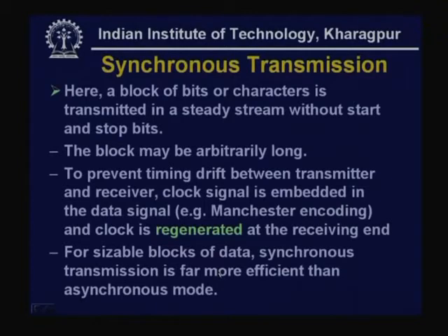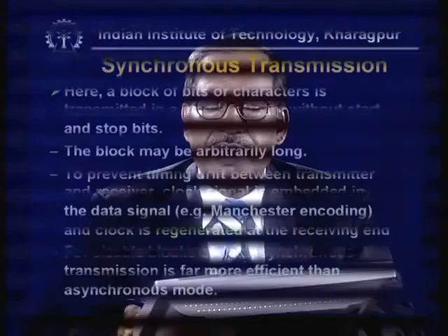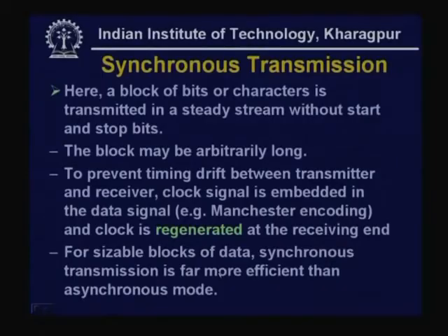However, asynchronous protocols are not very widely used because of the inefficiency or high overhead, and that is why synchronous transmission is commonly used. In synchronous transmission, a block of bits or characters is transmitted in a steady stream without start and stop bits. So a stream of characters or bits, it can be both, are sent one after the other without start bit overhead, and the block may be arbitrarily long.